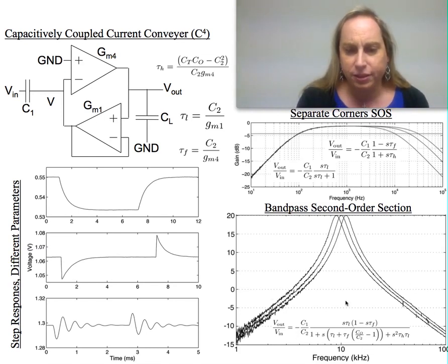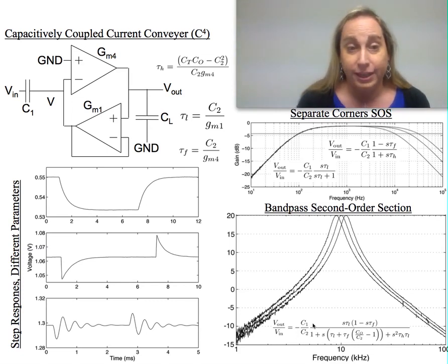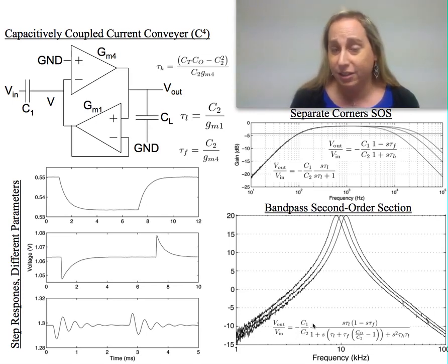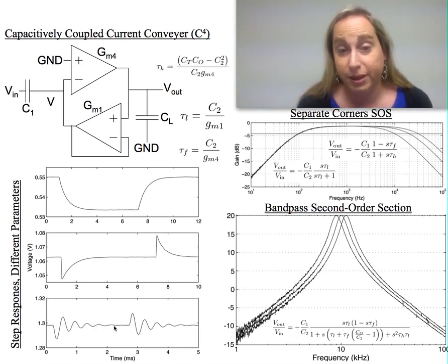The math gets a little more complex, but is still fairly reasonable all the way through. There's a whole set of conversations in terms of distortion and noise and other aspects, which are all fairly well modeled, but I just wanted to show that you can build a reasonably good bandpass filter structure out of this. If you look at the step response for it, you would see a ringing response that returns back to equilibrium, and the same thing in reverse for a step in the other direction.